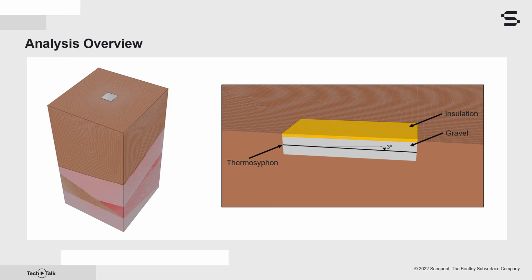The thermosyphons are sloped 3 degrees from a horizontal reference. They are 9.51 meters in length, 88.9 millimeters in diameter, and are 1 meter deep on average. Each thermosyphon evaporator is connected to a 6.5 square meter condenser. The condenser is not included in the model domain, as the thermosyphon boundary condition accounts for the whole thermosyphon system when applied to the outer surface of the cylinders representing the evaporators.